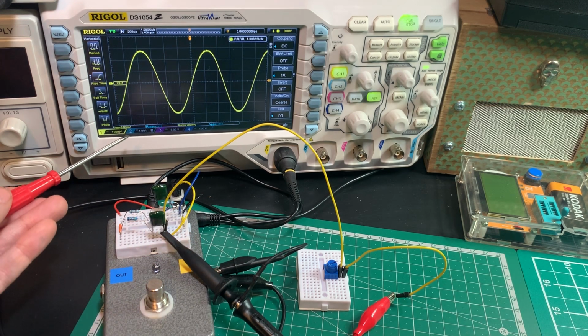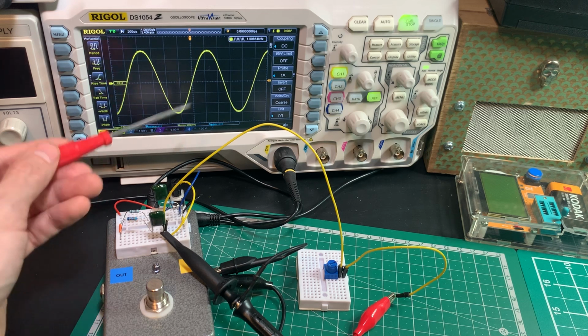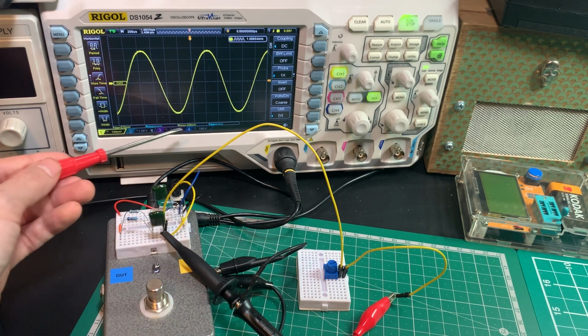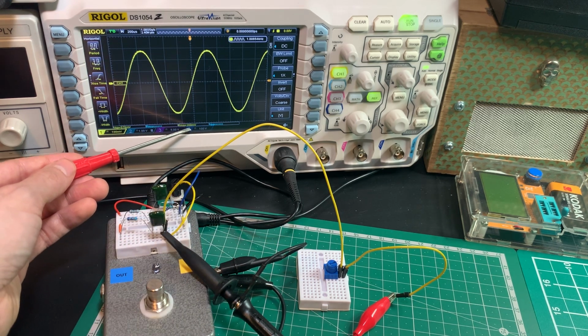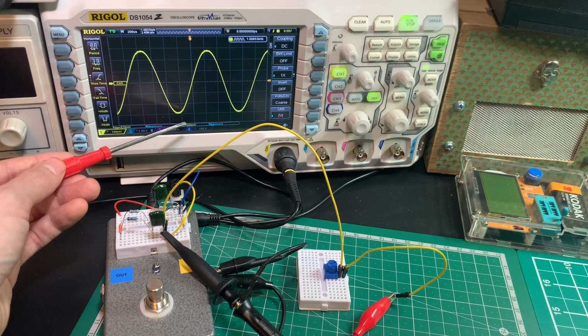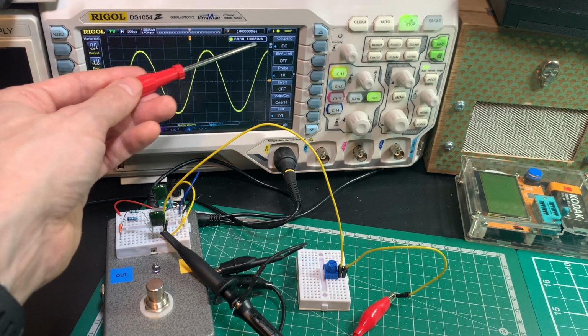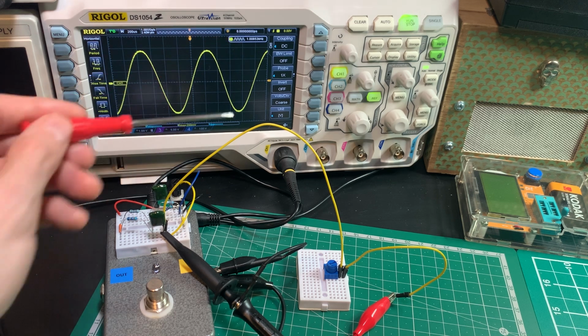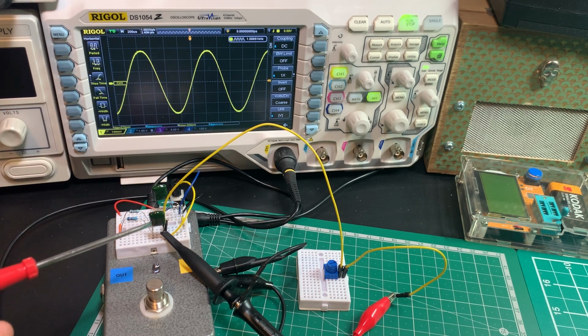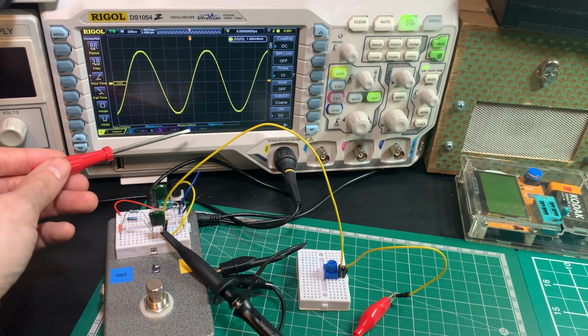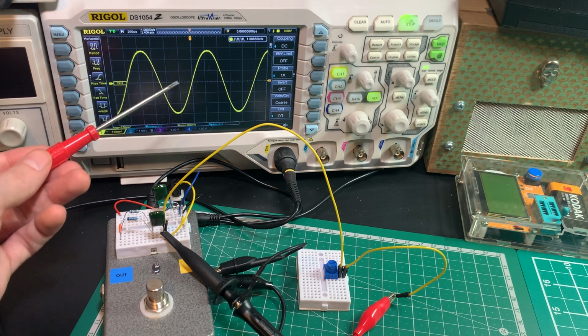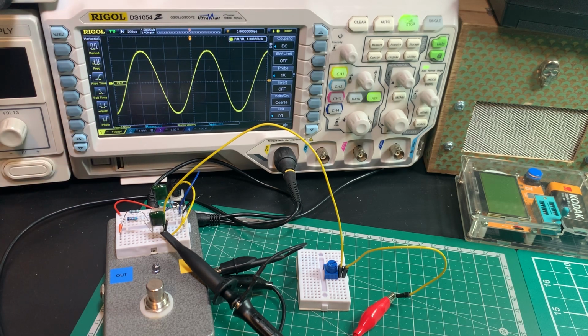So what I've got going on here is I'm setting up, by bypassing the potentiometer to begin with, 200 millivolts RMS at 1K in this case. As long as the frequency remains the same and is a frequency that's going to be used by the pedal, we're okay. I'm just using 200 millivolts because that's what I'm set up to, seems reasonable for this pedal, but all we really care about is when it gets to half that.